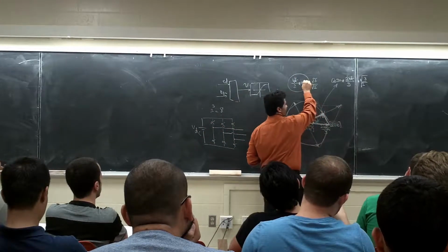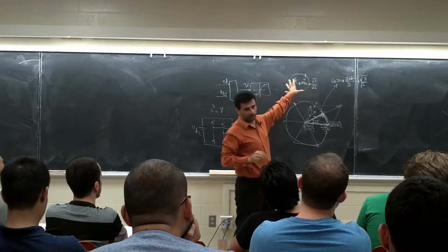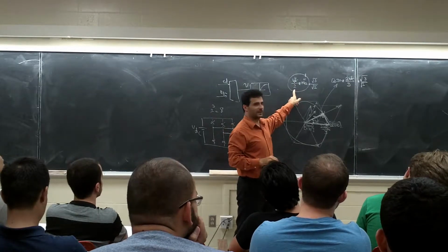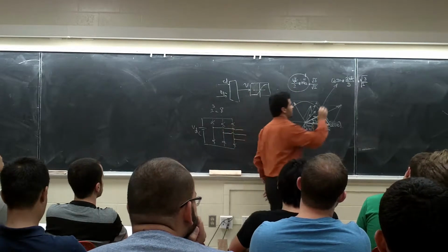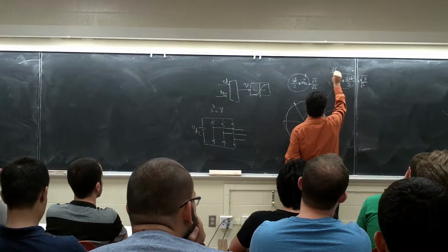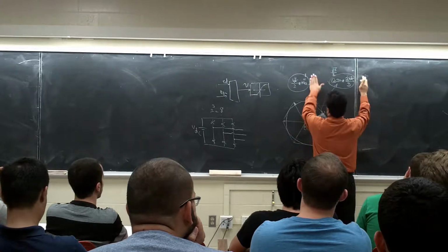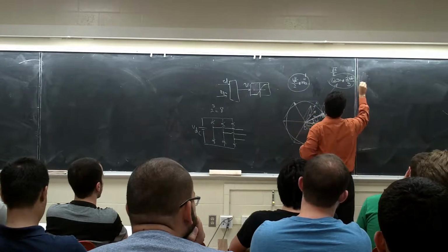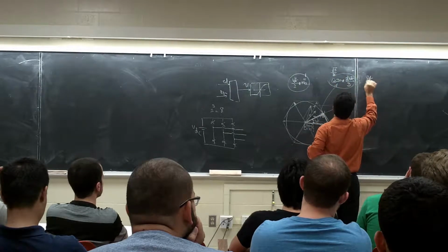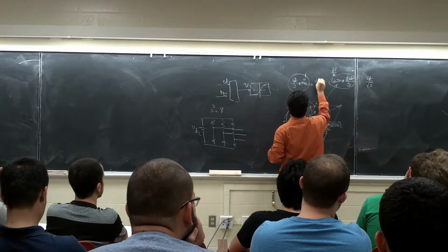And how much is the MA maximum here? 1, right? This is the maximum possible for the sine PWM. How much is this one? VDC over 2. How much is this one? Cosine of 30 is the square root of 3 over 2, if I'm correct, right? Yes. So basically, let's get rid of this one because this is the same for both of them. This one is going to be VDC over the square root of 3. Here is how much? VDC.